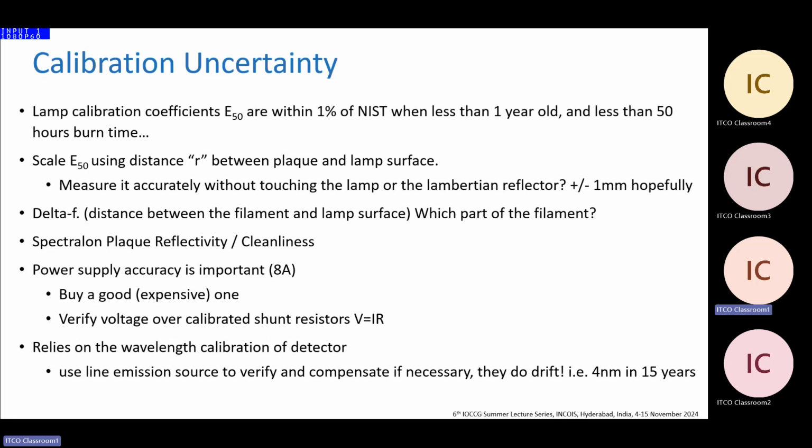The other thing about this is, we've got calibration coefficients that are spectral, but then we need to know what the spectrum of our sensor is. For the hyperOCRs, the diode array spectrometers, over time the band centers can drift. So before we calibrate, especially if the sensor's a few years old, you want to put your sensor in front of an emission line source to see if the lines have spread out over time.